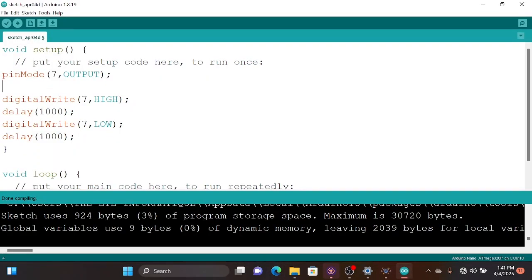So if you want to create a loop, you can use a while loop. So put in the command while(1). 1 is a condition there which signifies that it's always true. Then the operation has to enter within the braces of the while loop.